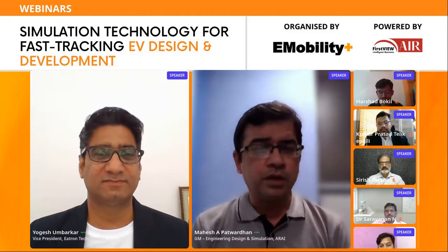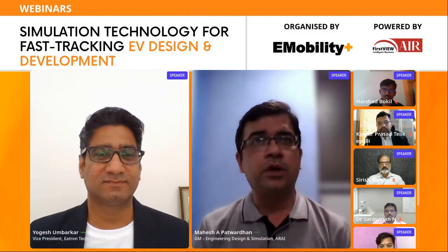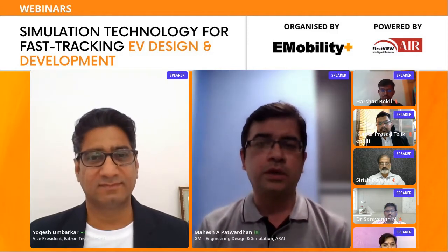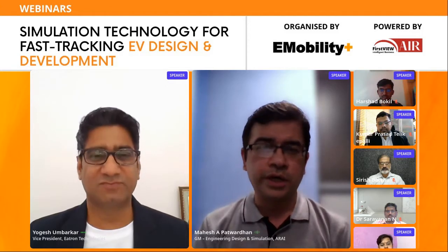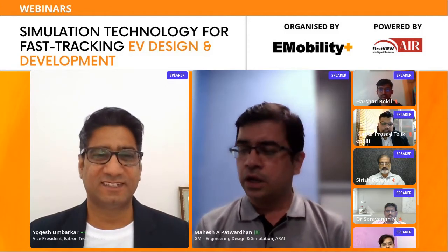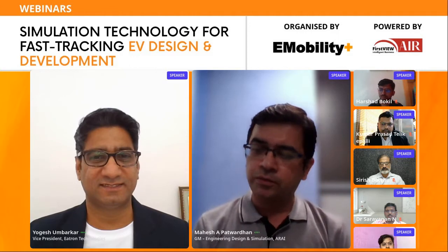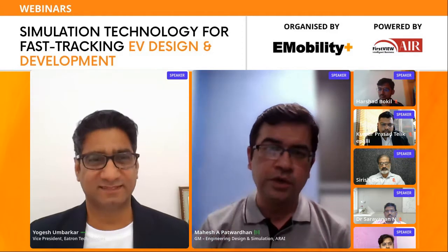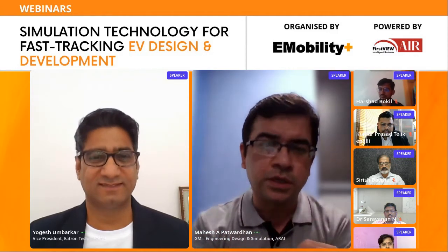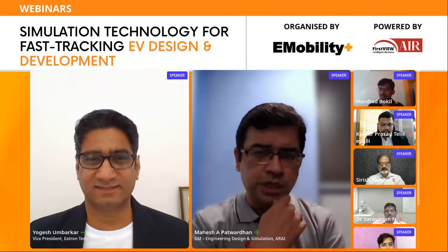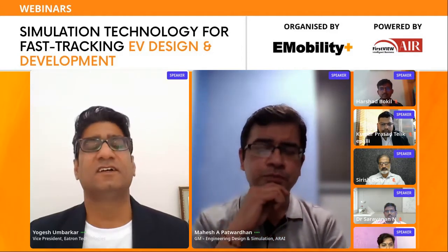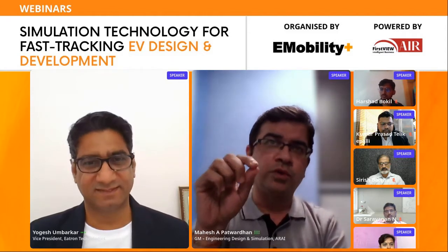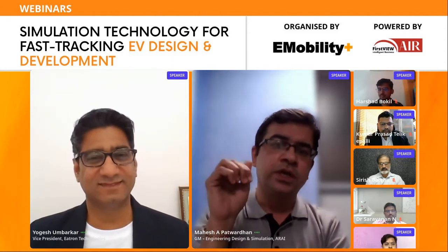People do that kind of thing with accelerated testing, but from a simulation perspective, there is still some work that needs to be put in. The third aspect is that we cannot do everything only through simulation, especially where EV thermal performance is concerned, because we require HPPC data for cell characterization, and to understand the behavior of a cell under electrical load and different charge-discharge cycles.